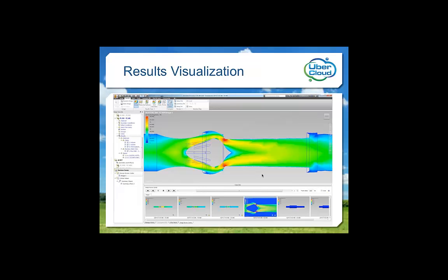There are many ways to view results in SimCFD, but this simple cross-section offers us a lot of information about the flow path. The abrupt changes in velocity magnitude that are observed will influence changes to the plug to smooth out the rise in velocity as the fluid approaches the restriction. Better management of velocity through the valve will reduce internal damage and vibration-induced noise.